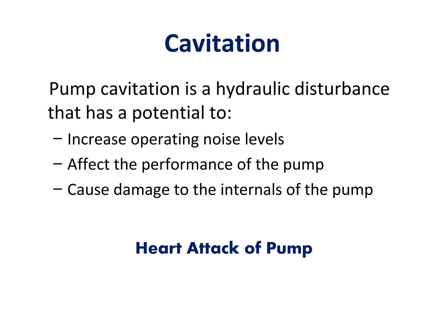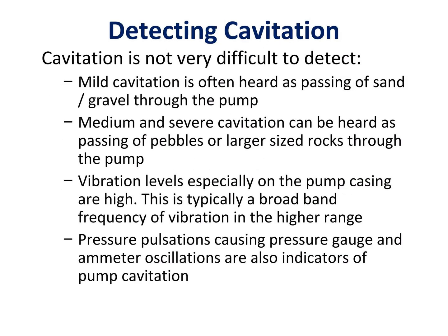That's the reason cavitation is also called the heart attack of the pump. The first question arises here: how do we know that the pump is cavitating, or how do we detect cavitation? It is not very difficult to detect cavitation. You can detect it by abnormal sound or vibration. It can also be detected by pulsation in the discharge pressure and the electric load.